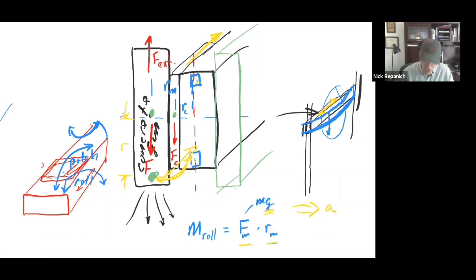Where is the center of mass below the axes? And then how much is it accelerating along here? What's A? And so F is center mass MA times R, and you have a yaw moment. The calculations really are that easy for the most part. Then you look up, and you say, okay, on this stage, the yaw moment it can handle is 14 Newton meters, and I calculated 4 Newton meters needed. Okay, good. 14, 4, therefore I have a safety factor of 3.5, right?